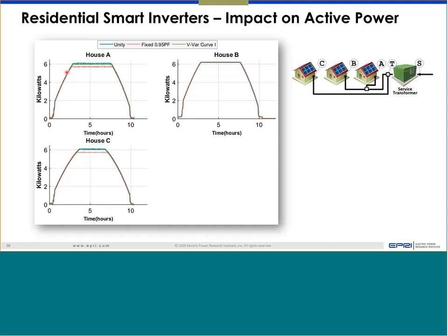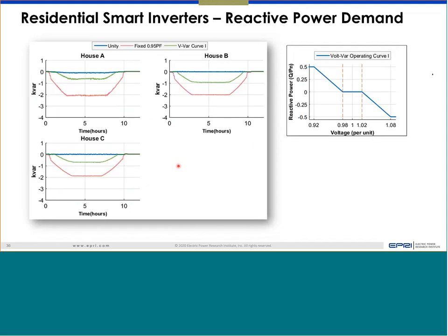One simple solution could be to use an inverter which is a little bit larger in size, at least where the VA rating is a little bit larger. So that will have a lot of room for reactive power support. Any questions or comments? Somebody unmuted? Okay, if not, let's move on.